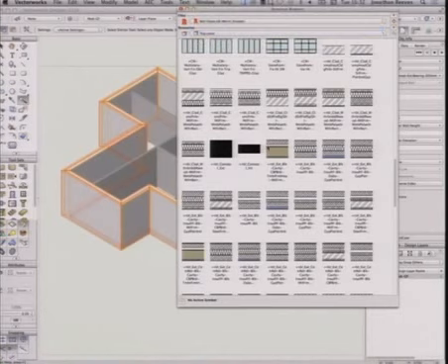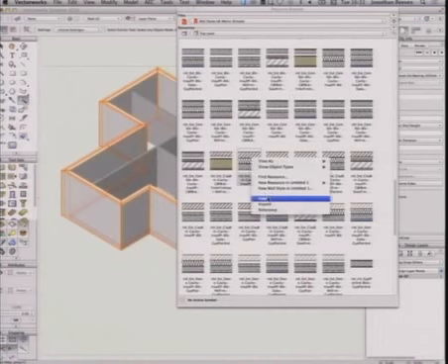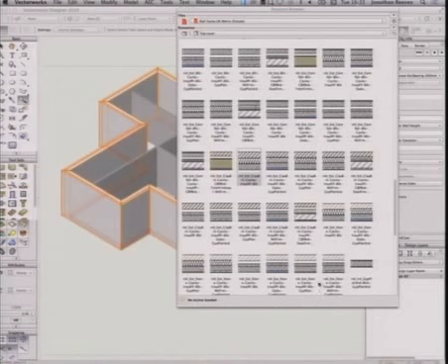Let's go for, flick over to something else, double click, and basically I can apply. So let's do a right click and apply. And when I come to replace those walls, I can choose which side of the wall, i.e. the inside face or the outside face I would like to reapply by. They're going to be different thicknesses. So this is really critical, how you replace your walls. You don't want your area getting bigger or the external part of the building getting larger.